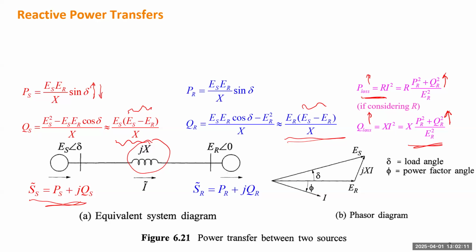In order to have reactive power flow, you need to have the gap. So this can never be zero, right? You will have a difference of voltages between any two neighboring substations. So if you want to deliver reactive power from one point to another, you will intentionally create such a voltage gradient to determine where the power flow will go.